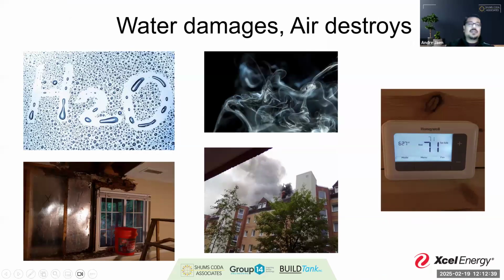So let's start with our water resistive barrier and let's start with sort of the exterior of the building as a whole. Now, water does damage, right? When water gets into assemblies, the first thing that starts to happen potentially is mildew or rot, and you're starting to degrade those building materials earlier than you are supposed to. You also can suffer from a freeze-thaw effect if you're in the right climates, like here in Colorado, where it's absolutely freezing outside these last couple of days.